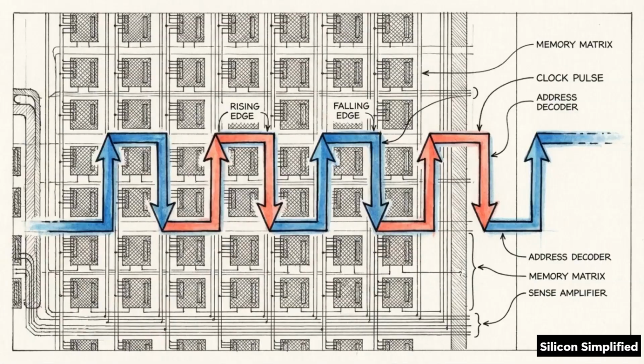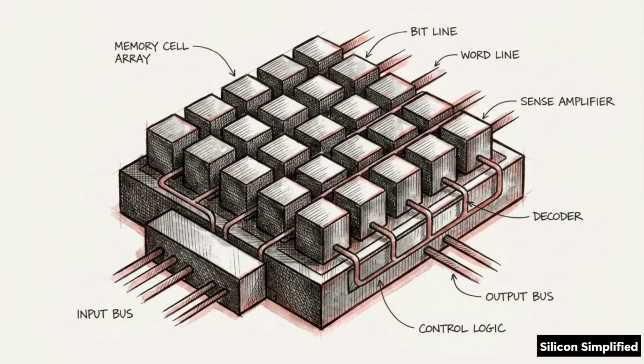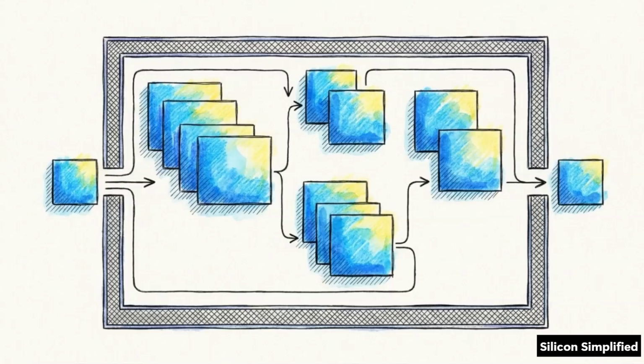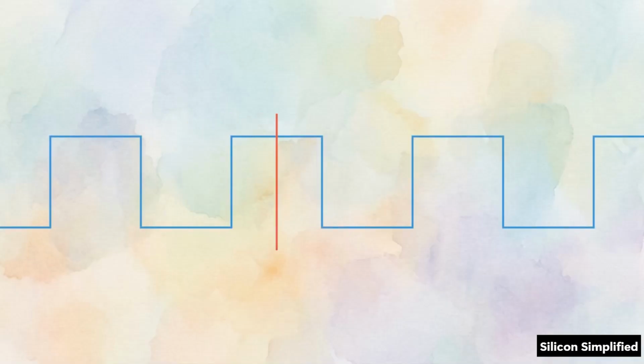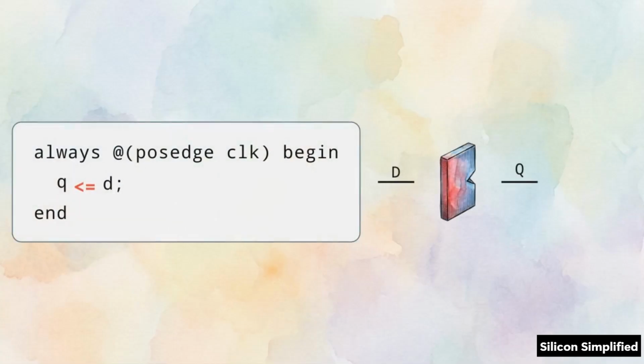This is sequential logic. To build hardware memory, Verilog groups instructions inside an always block, which is programmed to trigger only on the edge of that clock pulse. Inside this block, we use the non-blocking procedural assignment, represented by a less than sign and equal sign. This operator evaluates all incoming signals on the right simultaneously. It holds data in a temporary state, pushing updates to the left only when the time step ends.